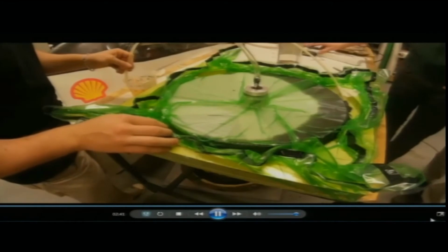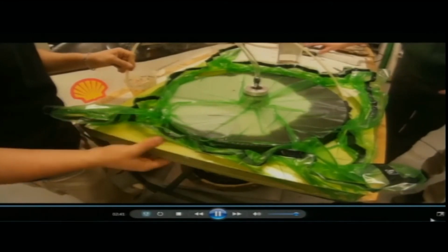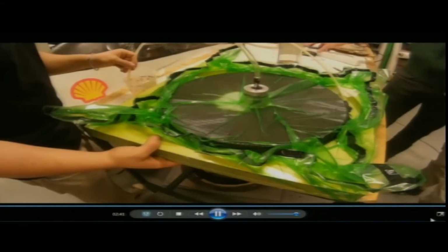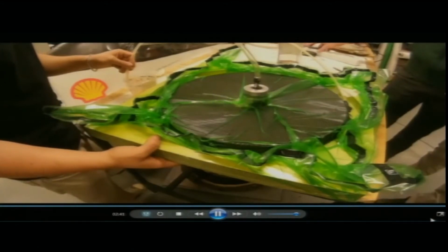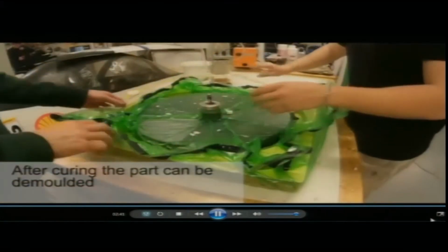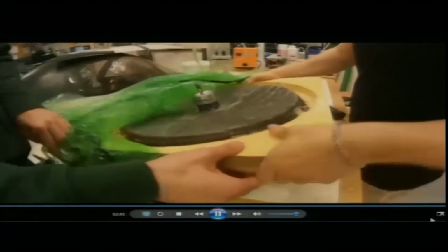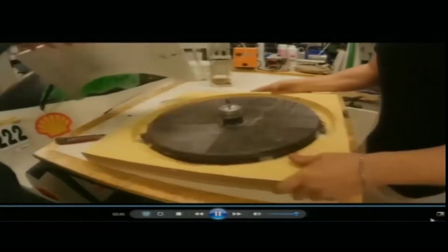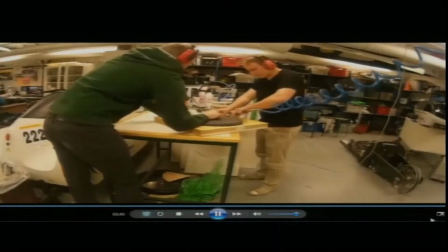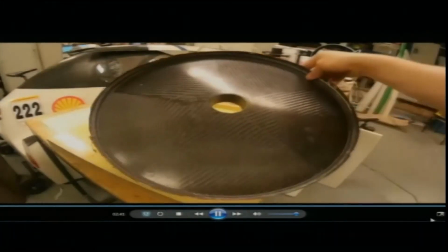So, epoxy resin is getting applied, and slowly you can see that vacuum that has been made, the resin is going everywhere nicely, it is spreading all around. And sometimes they also keep an additional bleeding pocket, so that no extra resin remains there. And now you see that they are just opening up the whole system, and that is where you have the disc. Incidentally, this type of disc is actually used in automobile brake discs and things like that. So, sports cars have a good demand for this type of carbon fiber reinforced discs.